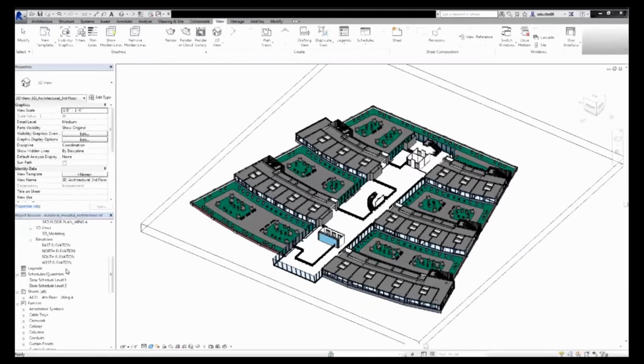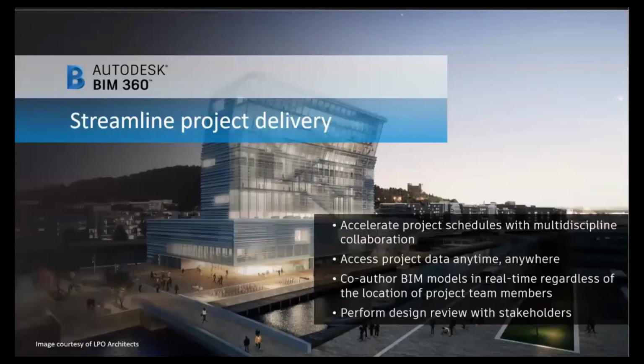And also, for updates, you can now create a 3D viewpoint within Navisworks, save that viewpoint and share that with your colleagues. And also, Autodesk updated the IFC file reader in Navisworks, where you can use the same open source code from Revit to handle IFC files with added hierarchy and data enhancement.